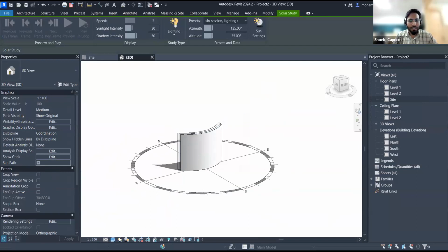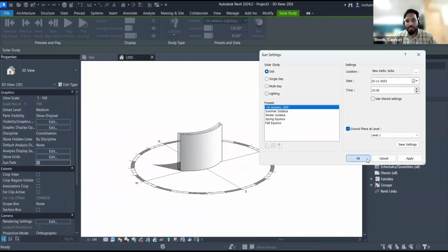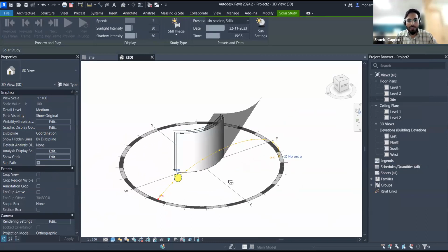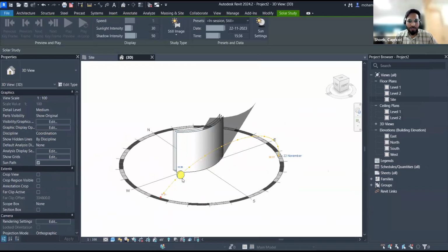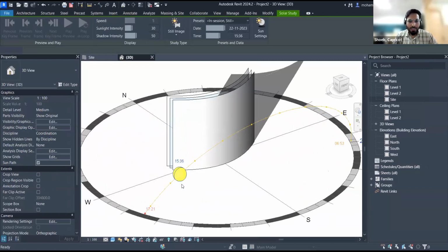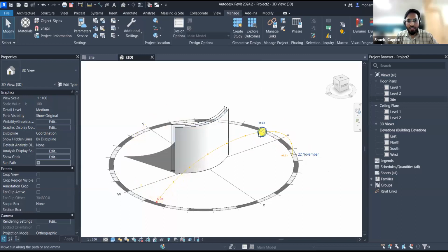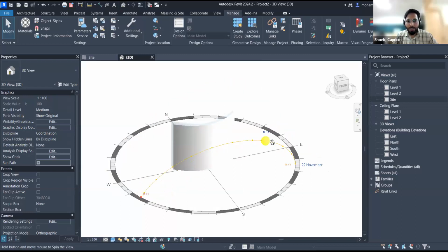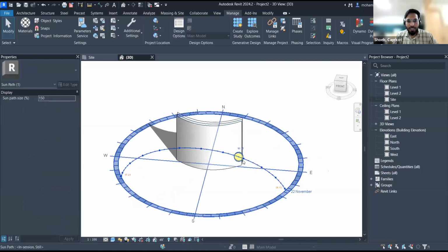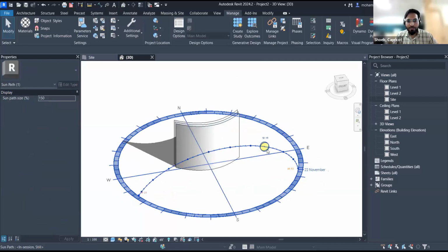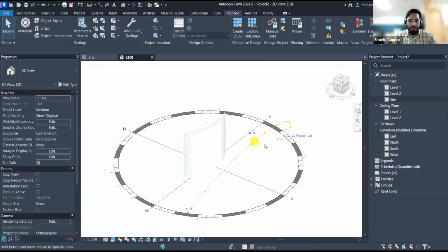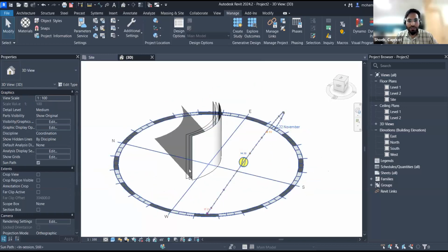So in this case, sun path can be switched on, and you can also, like I said, choose time and date. It is choosing the current time and date, and live sun input can be shown. You can also interact with this object, right? It's interactable. So if I interact manually, you can change the time over the day. So during the day, I'm going for a different time, and as you may notice, it is updating all those shadows live. So shadows are accurate in this case, and it's set for New Delhi location, right?